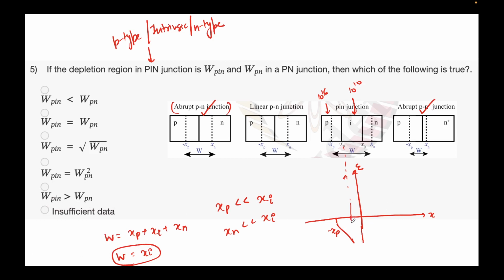Right, so it will peak here and then it will remain constant. Why constant? Because the electric field will remain constant, because there's no charge here in the intrinsic region. Remember that. It's not doped, there are no acceptors or donors in the intrinsic region, hence the charge will be 0 here. And again, when you come to the junction on the other side, it will rise again.